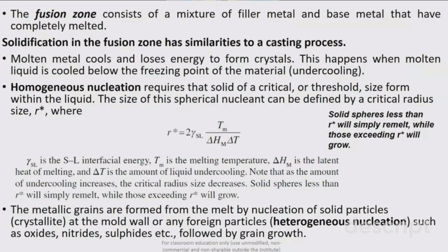If you remember the solidification of metal, you might have seen that it does not happen quickly. On reaching the freezing point, the solidification does not start immediately. For initiation or progression of the solidification, you require some lowering of your temperature below the freezing point. That lowering of the temperature below the freezing point is known as undercooling, and this is the driving force behind the solidification process.